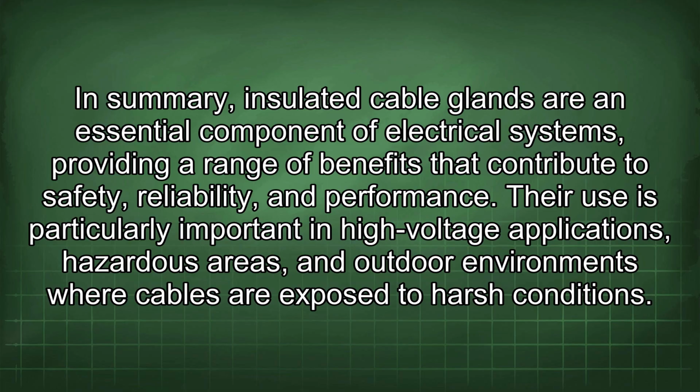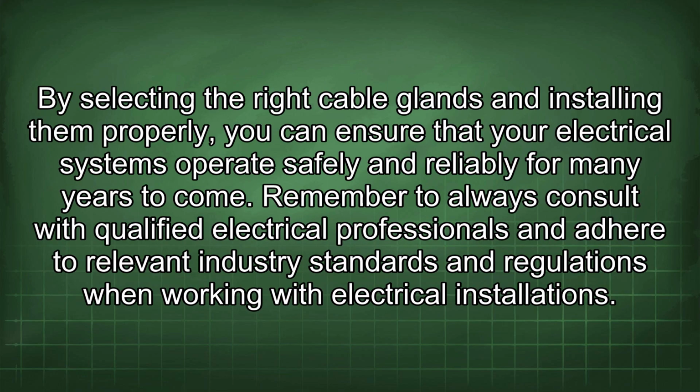In summary, insulated cable glands are an essential component of electrical systems, providing a range of benefits that contribute to safety, reliability, and performance. Their use is particularly important in high-voltage applications, hazardous areas, and outdoor environments where cables are exposed to harsh conditions. By selecting the right cable glands and installing them properly, you can ensure that your electrical systems operate safely and reliably for many years to come.